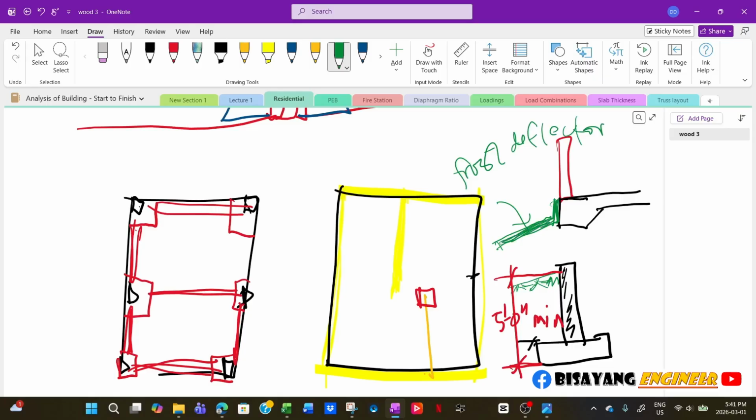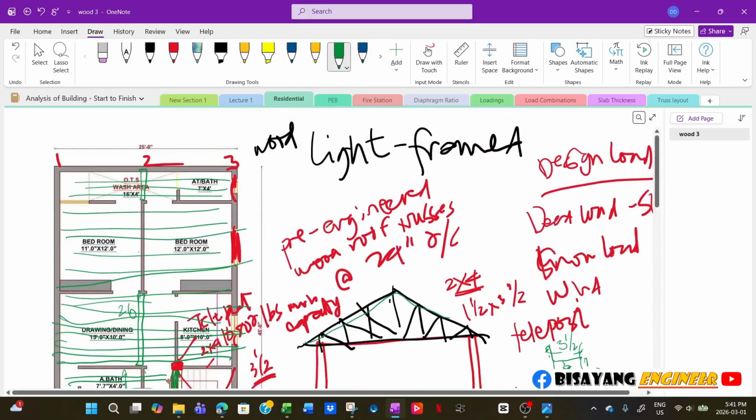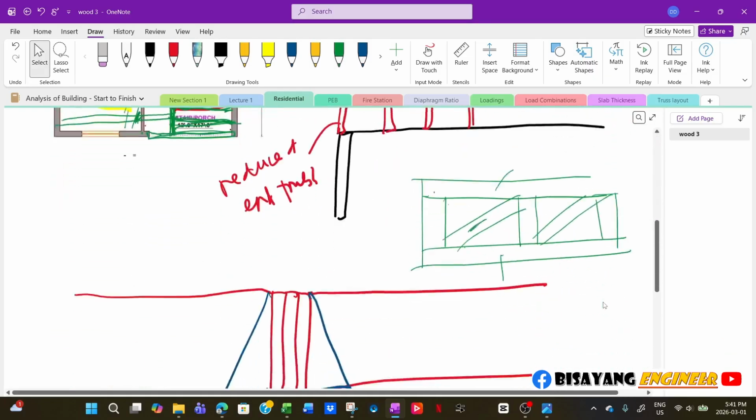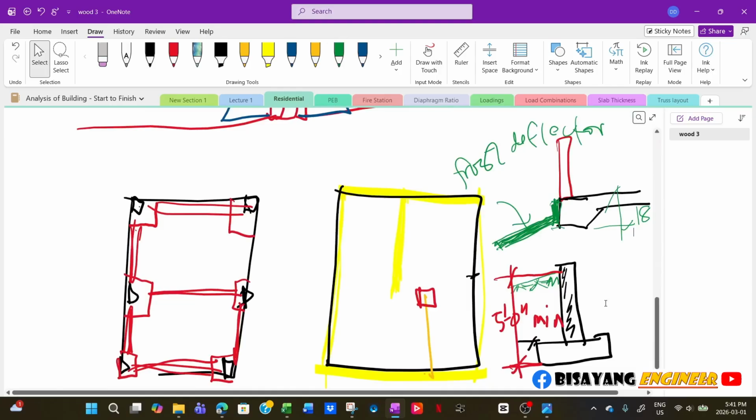There are requirements for the R value of this insulation. Sometimes it will be 5 inches thick insulation, 4 inches. It really depends on the R value requirements. But this is typically 18 inches thick around the perimeter. So those are the other options.